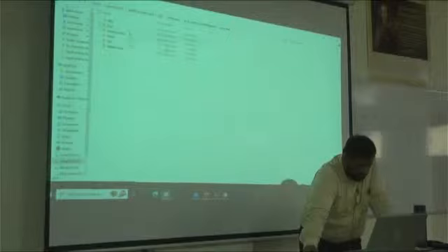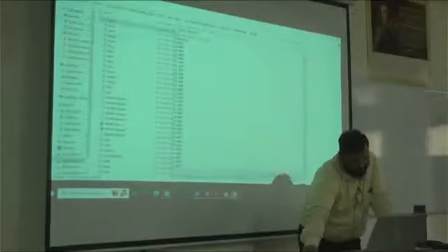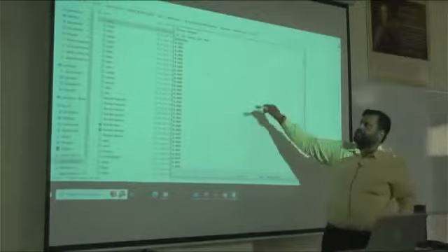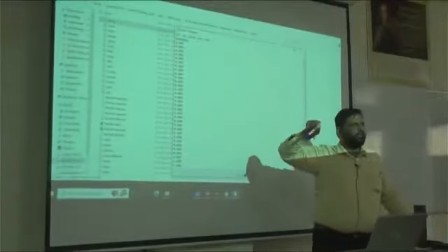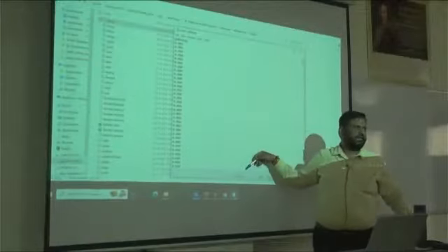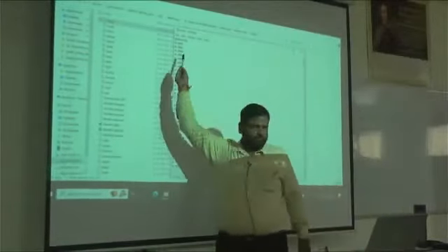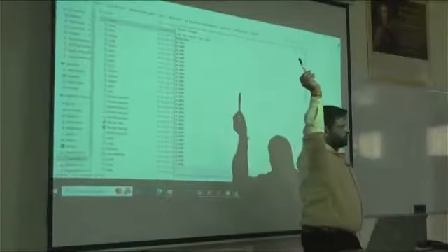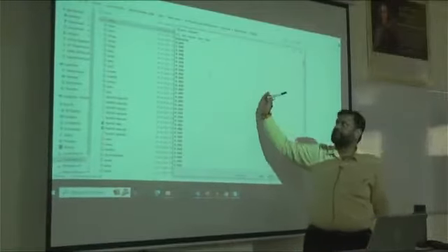So like that, first I show you the weather data. If you have basin station data, then you have to create the text file for each individual station. Or if you are using grid data, for each individual grid you have to create a single text file like that. The first row would mention the year 2001, 01 is the month, 01 is the date, so 1st January 2001 will read like that.